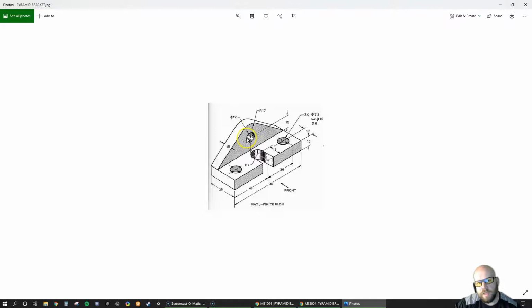But if I'm going to create this front view, the way someone would make this is they would create sort of the whole outside of this, okay, and then cut away this piece here, okay? Or they might make it from an angle bracket. There's no indication here that this is made off of an angle bracket.